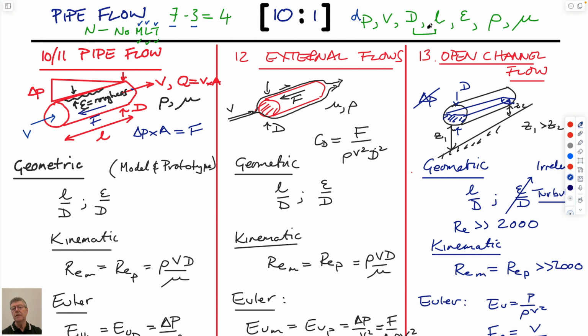And so we can start grouping these variables. We could use Buckingham Pi, which is a very formal way of doing it, or we could start guessing what they would be. These are units of length, length, and length only. So the units of length on length describes one potential variable. Roughness divided by diameter. This could also be roughness divided by length, I suppose, but not so relevant, right? You think that in closing off the diameter of the pipe, the roughness would have more of an effect there than over the length. So let's not think about this as a potential.